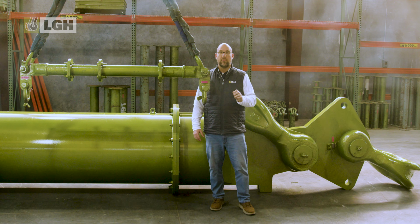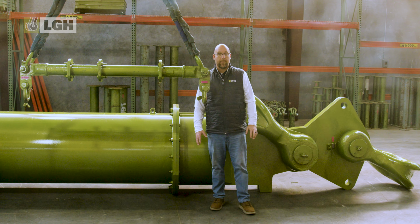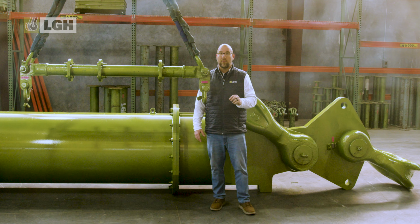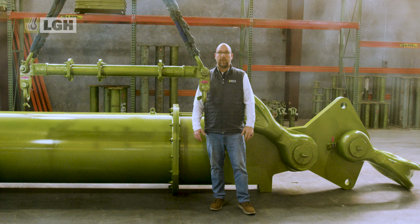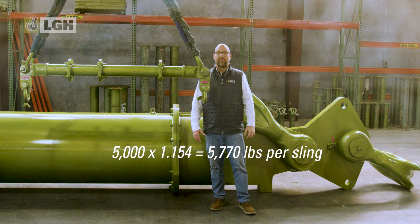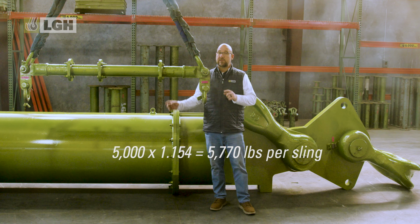We must account for sling angle tension in our calculations. For example, with a 60-degree sling angle, the tension factor is 1.154. We will take a closer look at a tension factor graph in a moment. Therefore, the actual tension in each sling is 5,000 times 1.154, which equals 5,770 pounds per sling.